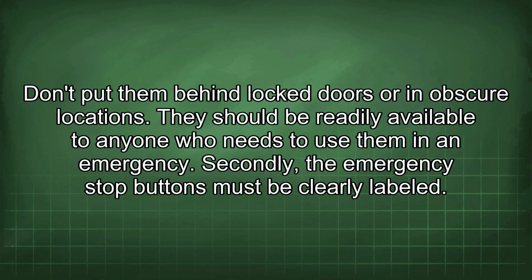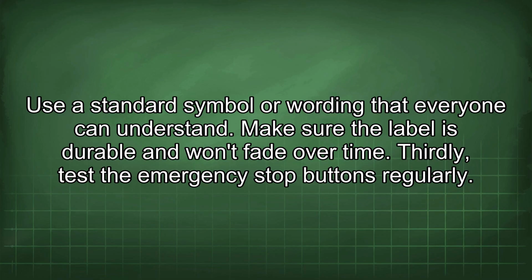Secondly, the emergency stop buttons must be clearly labeled. Use a standard symbol or wording that everyone can understand. Make sure the label is durable and won't fade over time.